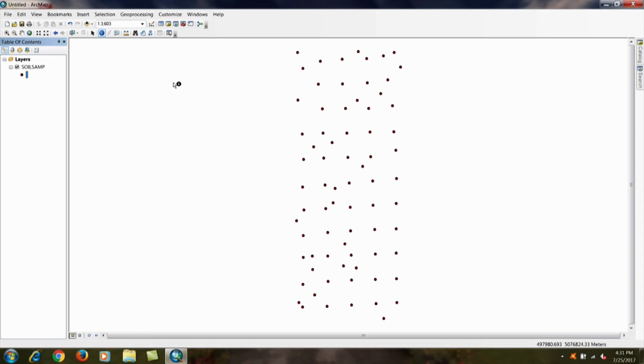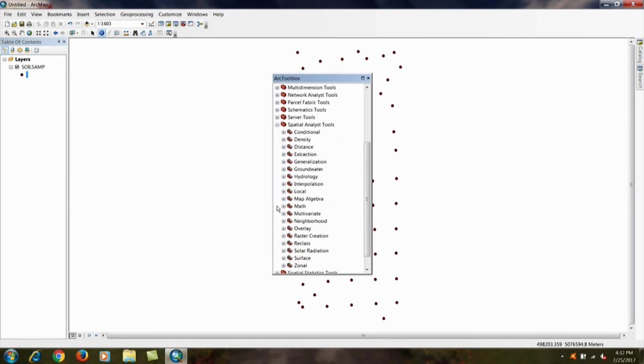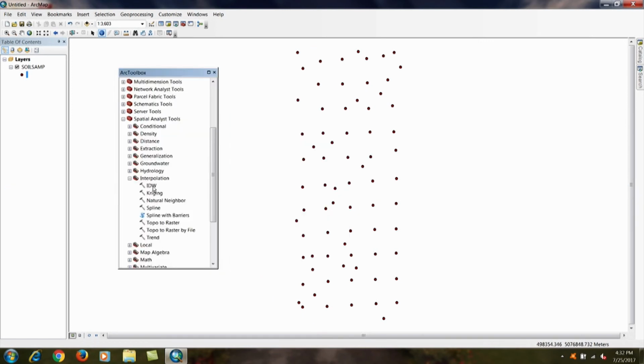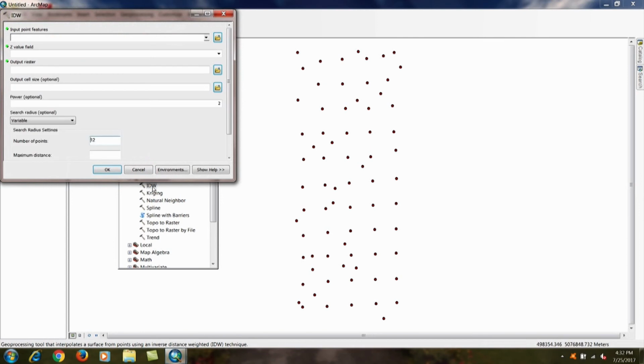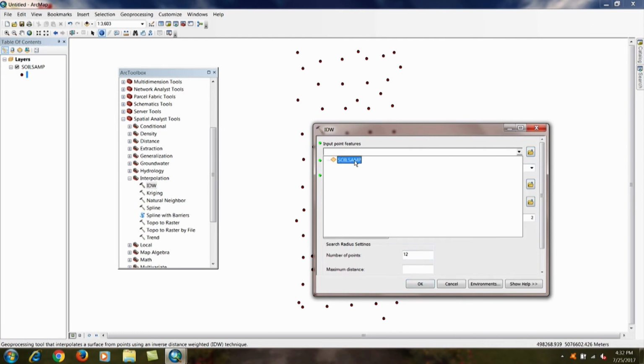again I am using ArcMap and ArcGIS software. Here we have to use some tools which are available within this software. When we install this, a Spatial Analyst extension is also installed. So, I will go to that, and then interpolation options, and for example, I will go for IDW. We already have point data, so now I will take the point data file here,